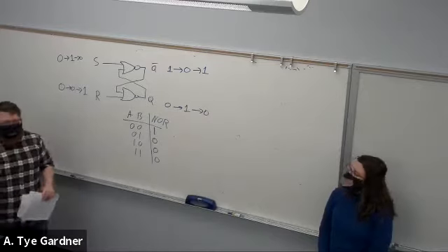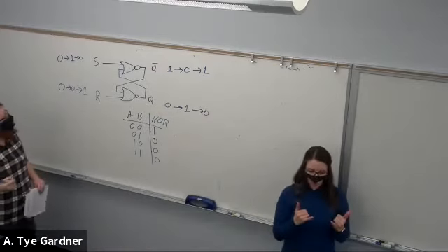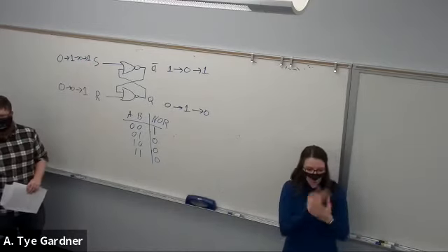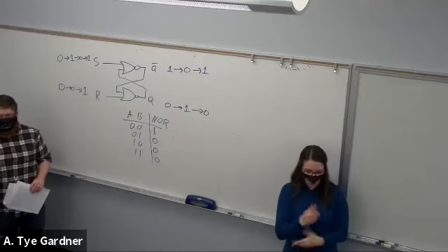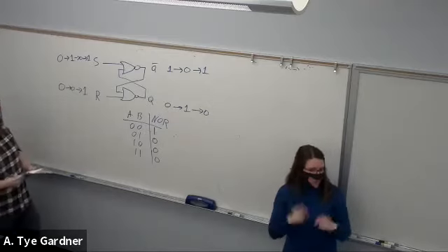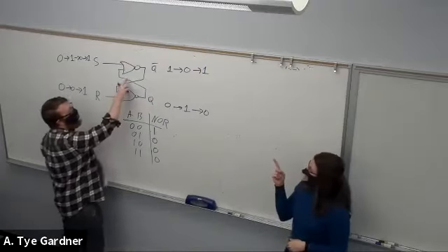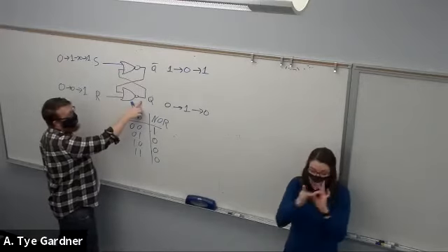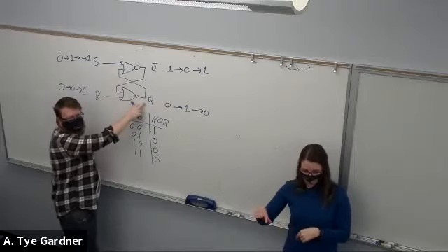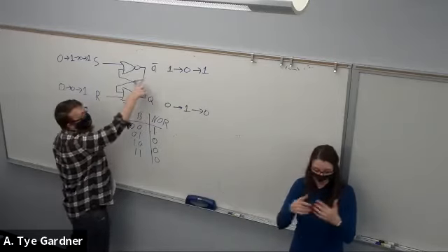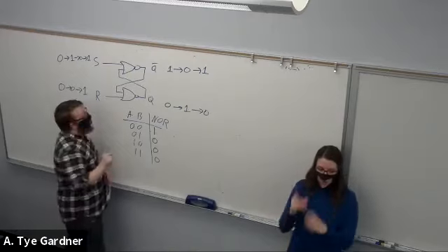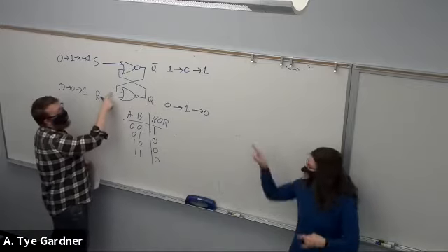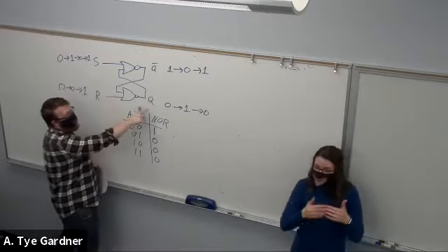All right. Let's look at one weird situation where I then transition so that they're both 1. Both set and reset are 1. What happens? Well, the output of the first NOR gate is tied strictly to set and Q. But if set is 1, regardless of what the output of Q is doing, the output is 1. Similarly, the second NOR gate, if reset is 1, regardless of what Q bar is doing, the output is 1.